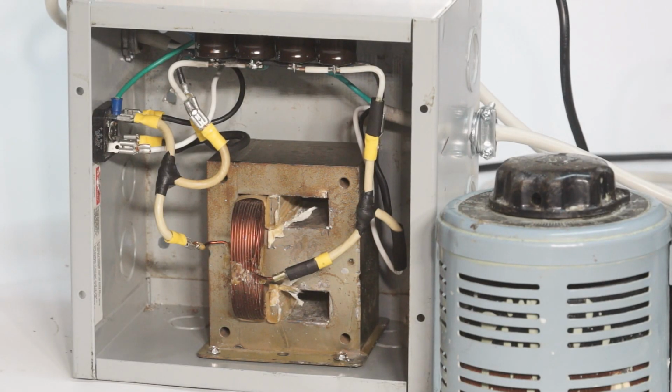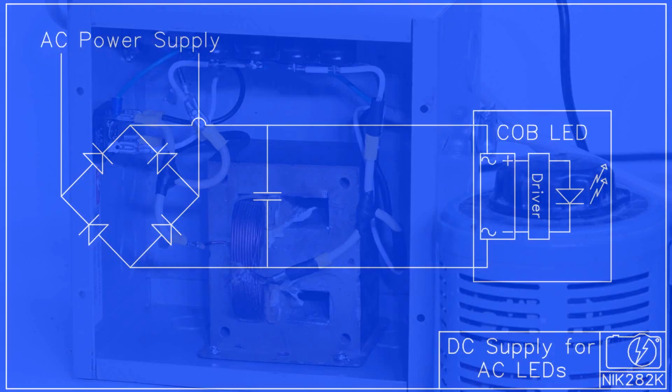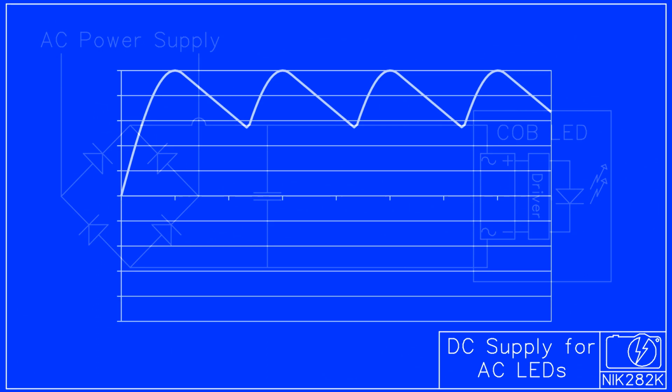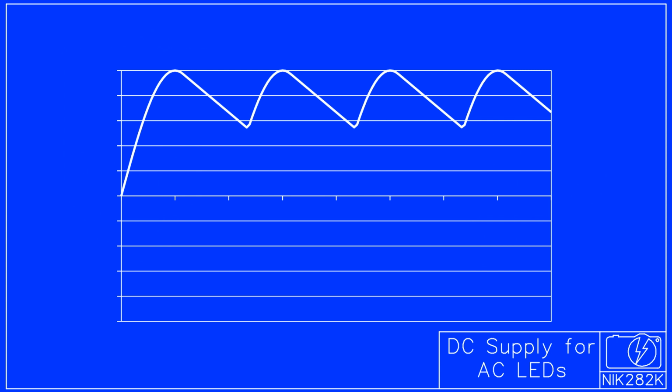This power supply uses some capacitors, a rectifier, and a large inductor to supply a smooth DC source to these LEDs, eliminating the ripple in its supply and therefore eliminating the pulsing of the light output. My first attempt used only a rectifier and a capacitor, which worked fairly well but still left about a 20-volt ripple in the power which was arriving at the LEDs.